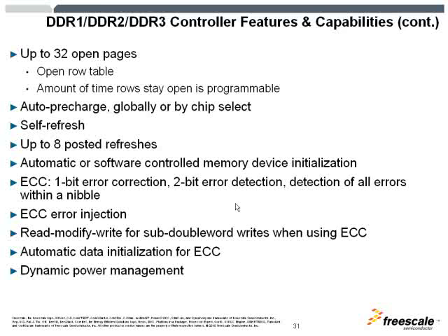The automatic data initialization for ECC is also available. This is a very nice feature where you want to initialize the entire SDRAM area, and all you need to do is select that bit, and after initialization of the memory controller, it will initialize the entire SDRAM for you with the value that you want. Dynamic power management is also available.